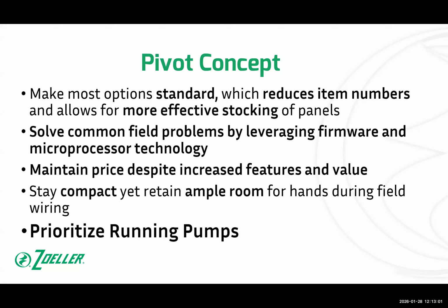And so it makes ordering one of these control panels very simple, because now really all you need to pay attention to is, what's your voltage and phase, how many amps are your pumps going to run, so that you match the core electrical components up. But in terms of functionality, these control panels come loaded, and you can use what you want. You can ignore what you don't want, but it's there. You don't have to special order this stuff.